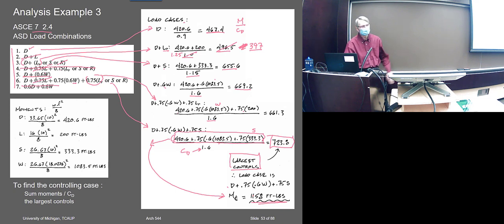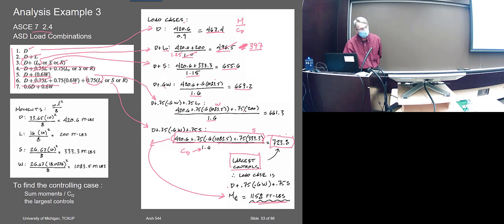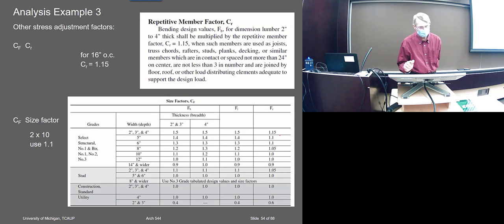Okay, so it's a bit to go through to decide, but you can see this is kind of an extreme example deliberately with the roof because it's got all the different loads in it. And you can see you've got several combinations that could potentially apply, right? How many do we have? 1, 2, 3, 4, 5, 6 different combinations. So of those 6, it's not immediately apparent which one would control. I can't think how you'd guess unless you actually went through this calculation and then determined which is the controlling one. Okay, so we got it. So that's the controlling one.